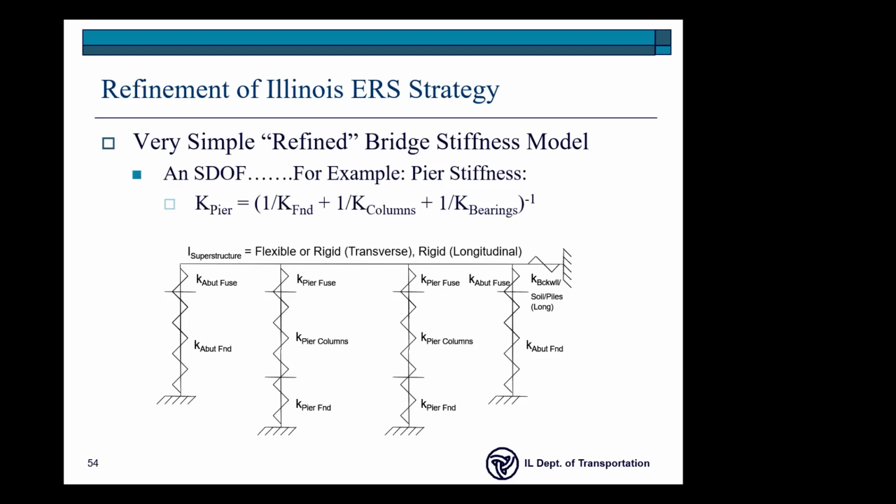When I read the design memo from Washington DOT, they are limiting MSE abutment bridges to a maximum of one span, 3 or 4 meter high abutments, stuff like that. That was 3 years ago, so I don't know if they've updated it, but there's a limit on what you can do with these types of bridges.